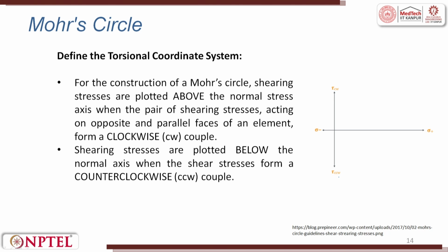So, you will have tau kept on the top as well as tau here and here. So, this is clockwise, this is counterclockwise. Shear stress are plotted below the normal axis when the shear stress form a counterclockwise couple. So, this is clockwise couple, this is counterclockwise couple.